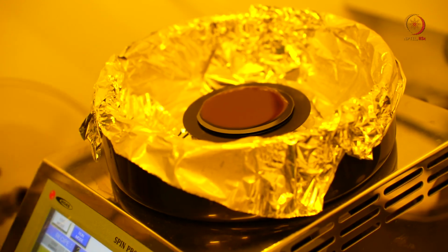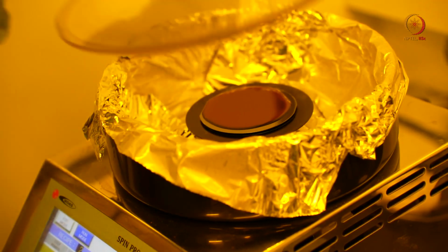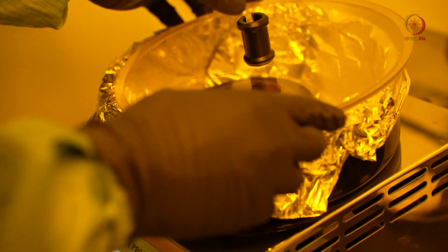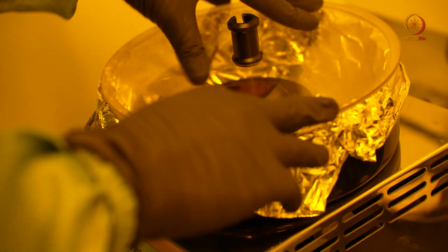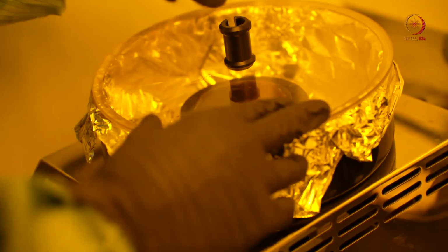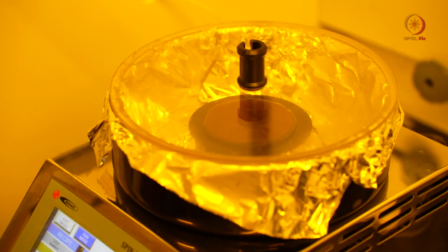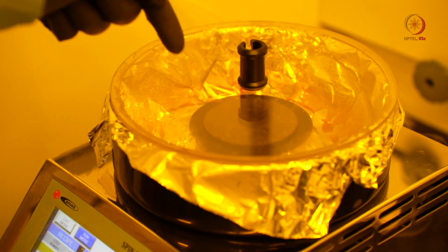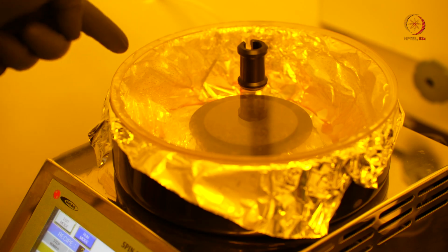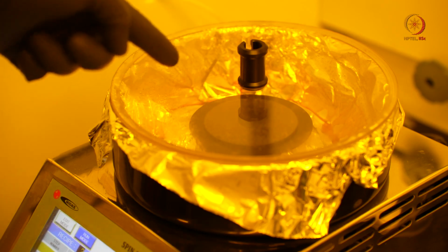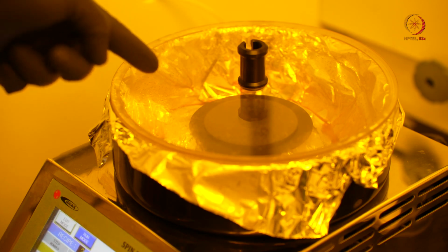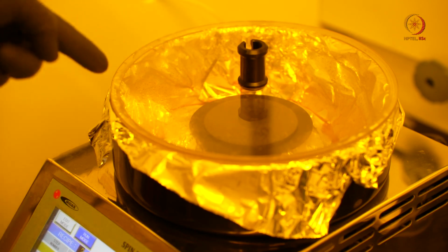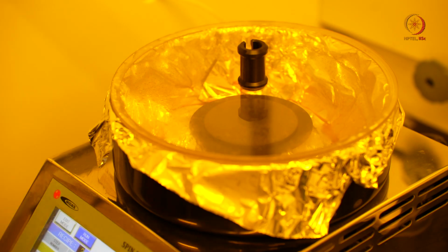Okay, now we can close the lid so that while spin coating it doesn't spill out. Right? Good. Now we will start the spin coating process. So if you look at the wafer, it will start rotating now. So you can see the excess photoresist that spilled over to the sides. That's why we have put aluminum foil, right? And you can see now the wafer is rotating at very high speed. It will rotate for 40 seconds at 3000 RPM, then decelerate back to rest.